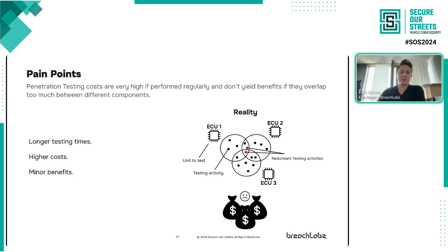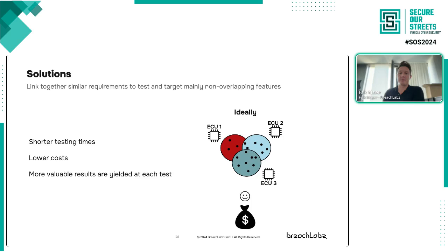Right, and then the idea would be basically that the scoping has to be aligned with the manufacturer first, which is usually already the case, and then the manufacturer that has the overview of all the different ECUs and their testing scopes can then, for example, say, okay, there's an overlap, so you don't have to test your communication line, for example, if it implements everything properly.